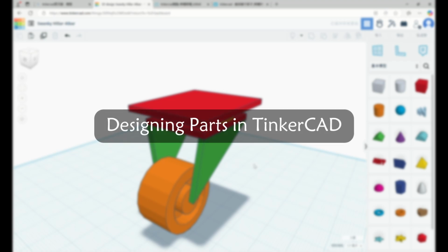Today, we learned how to design parts in TinkerCAD with a few examples. We explained the design process, including how to break down complex parts into simple shapes, how to resize, align shapes, and group them. We also learned the basic operations in TinkerCAD: adding, cutting, and mirroring. These operations are key skills in the design process, and once mastered, you will be able to design more complex parts in TinkerCAD, laying a solid foundation for future robot design.